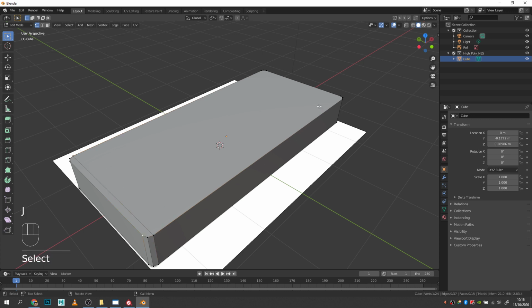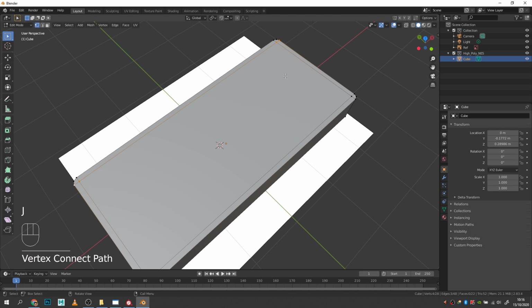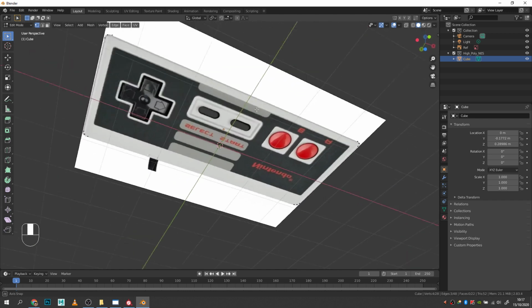And then the same this way, so this one to that one, press J, and then the same on the other side, and we're just working our way around, so make sure you press J, not Control. Working our way around, just adding these edges in. Now what those edges are doing is it's making sure that our middle face is 4 sides, that these are 4 sides, and that these are 4 sides. Okay, these pieces along here. So do exactly the same on the underside.